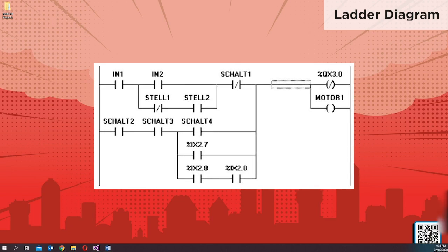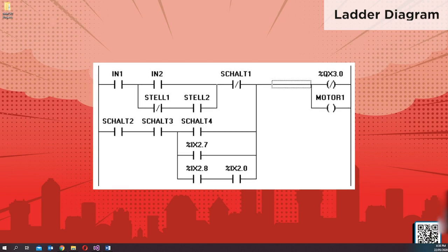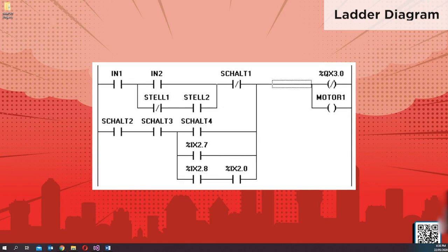On the other hand, one can also create networks as in FBD. The ladder diagram consists of a series of networks. A network is limited on the left and right sides by a left and right vertical current line. In the middle is a circuit diagram made up of contacts, coils, and connecting lines. The contacts can be any inputs, switches from actual hardware, while the coils can be any actuators, pneumatic valves, relays, and lamps.